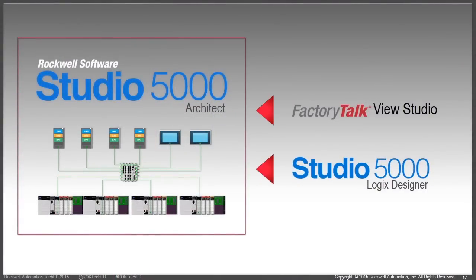Once you do the first commit process, you can now launch from this layout into the individual designers by either selecting from your Project Explorer or right-clicking on a device and say, Open in Designer. It'll take you right into FactoryTalk View or Logix Designer with that project open. From that designer, you can now make changes. The changes that you make in either FactoryTalk View or Logix Designer can then be synchronized back into the Studio 5000 Architect project to keep everything updated.